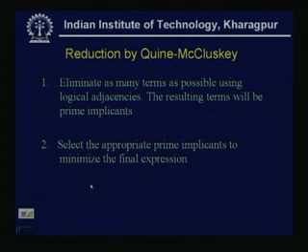Now, there are some disadvantages of these. So far we have discussed that K-map method. See, if it is for larger variables, what we have seen is that for n variable functions, the number of minterms will be 2 to the power n. So, say for 4 variable functions, the map becomes a 4 by 4 table. If it is a 5 variable function, then it will be 2 to the power 5, means this will be 32.